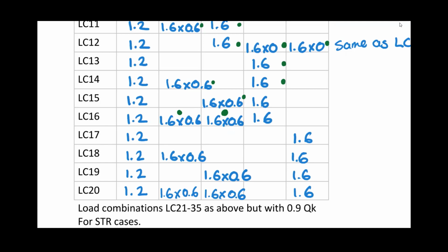Then we do the exact same thing now with wind case 2, and run through that and then combine it with everything else. Once again, we do not combine the wind loads together because they do not act at the same time. Either it's load from the one way or it's load from the other way. They can't act together. If you do have, for instance, a 45-degree wind load case for an unusual structure, you would treat that as a separate wind load W3.